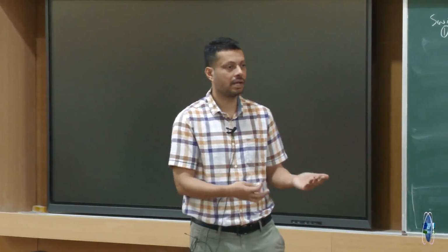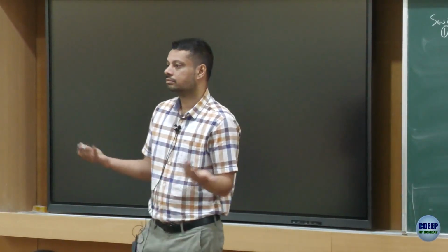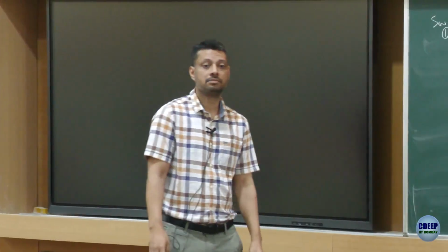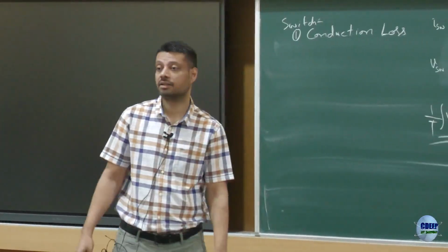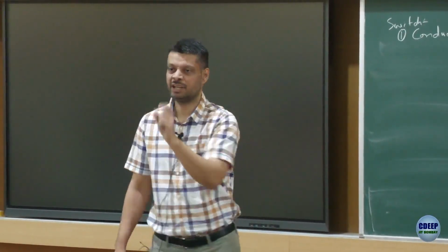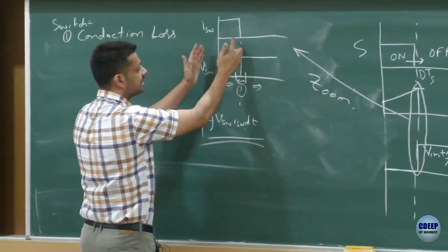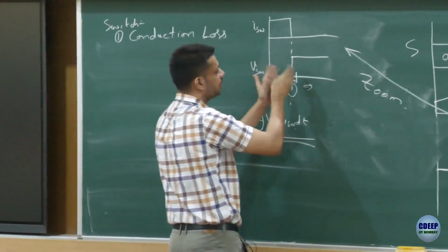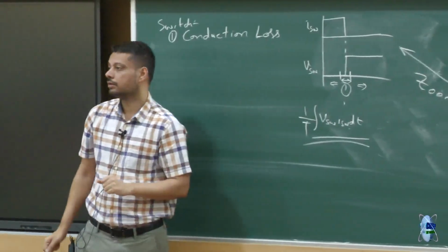Anything, I mean you think small, large, infinite, zero, comparable to conduction loss. More than conduction loss, okay. Any other thought? What could be integral Vi dt? If I just integrated over this small period, I am not integrating, this I have done the integration, this big period, this also I have done, this I have neglected anyways, now I am integrating over this small period. Should be, who said small? Okay. More than conduction, small. It's not in saturation, it's in linear region.